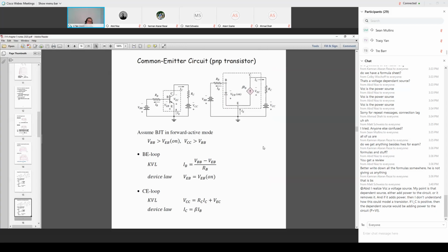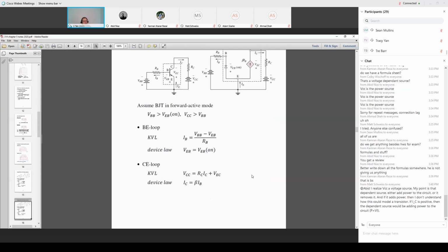So the external voltage VBB flips polarity, VCC flips polarity, and the internal voltage drop too. Now, the important thing is that because it's a PNP, we care about the voltage VEB when it's on, and the external voltage is VEC. Measure that. Equation-wise, you can say it's almost a side-by-side duplication.